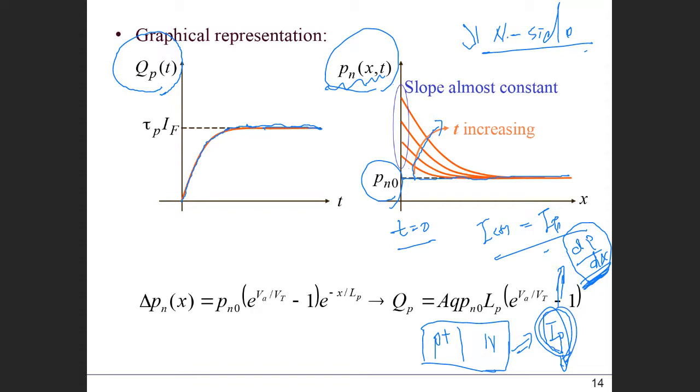Okay, so if you understand this one, now for our switching characteristic at t equals 0, on the outside we suddenly put the diode with this IF, forward bias current. Okay, which means that during this switching time, our current should be constant at IF. That constant is represented especially in this minority carrier distribution by this slope.